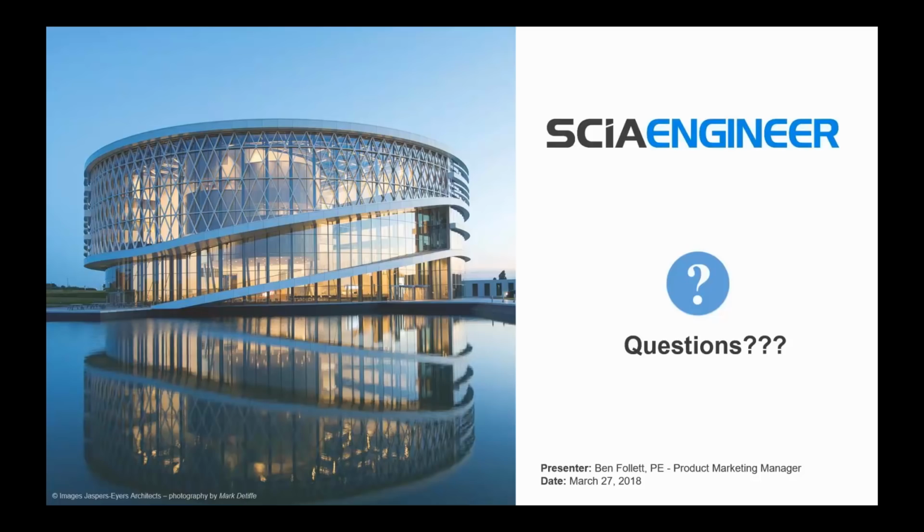Obviously, if you put a top on the structure, it would certainly affect the loading of the structure. You'd have loads on the roof. You also probably wouldn't need to put in the wind girts because the roof structure would be bracing the top of the wall. So all those things would come into account when you're doing the analysis and the design.